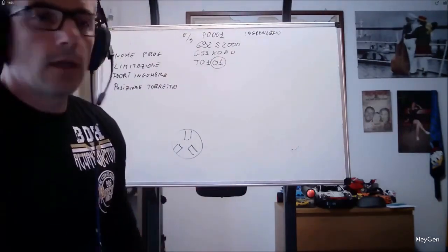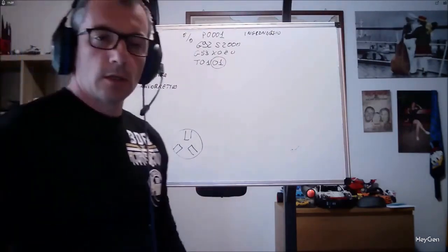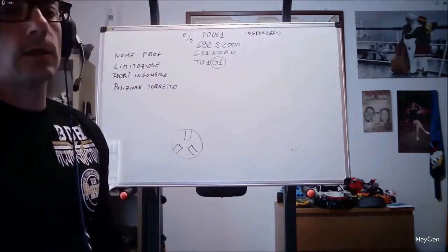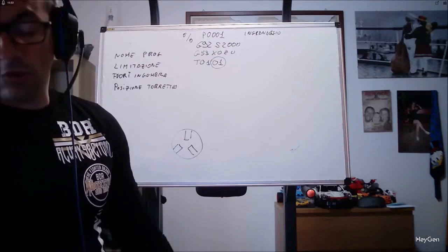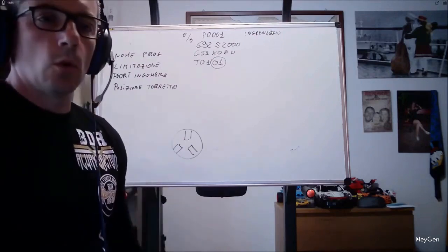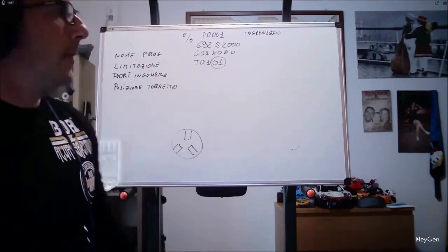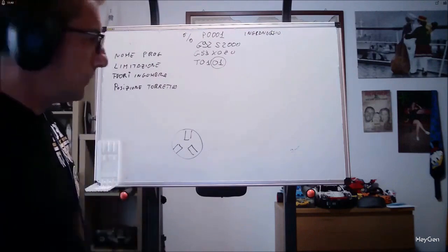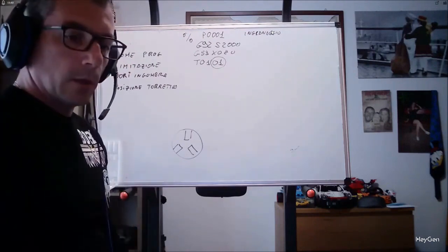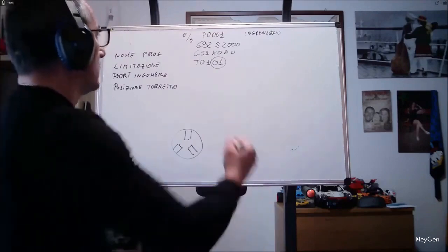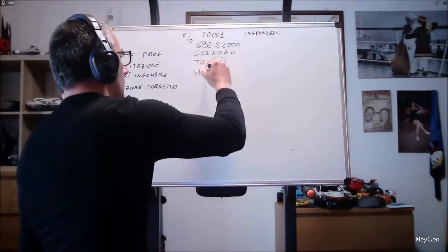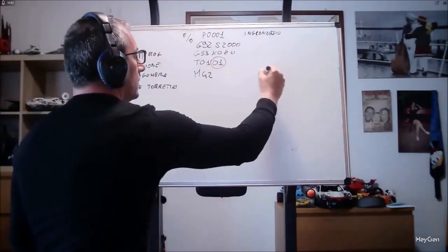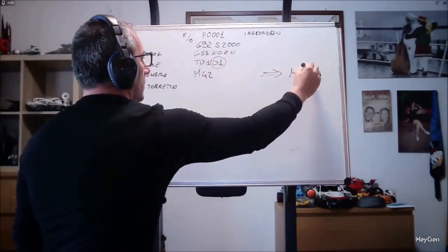The range, that is the gear, neither more nor less, the gears of the car. The car has 6 gears, the lathe has 1, so none for small lathes, 2, or 3. M41, M42, normally, so 2 ranges. If we do not specify it, the lathe will start in the last range set, M42, high range, or M41, low range.